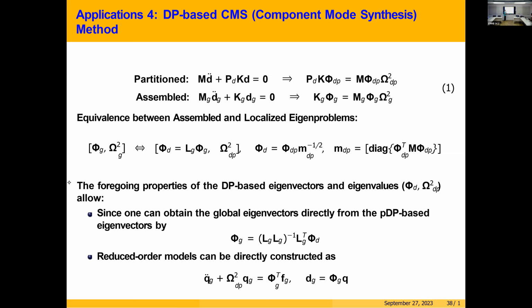Therefore, we don't need to go through choosing substructure 1 with 10 modes, substructure 2 with 20 modes, substructure 3 with 50 modes, nothing. This is it. Once you do it in an eigenvalue package, you can have the lowest 5, lowest 7, lowest 10 modes. You get it? You have the eigenvector. You have a reduced order model. Period.